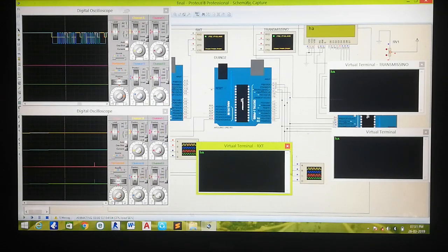Okay, this is the thing, and over here is the display part, so whatever I'm typing here will be displayed over here. By using all this protocol conversion, we converted I2C to SPI. This is a major part of our project actually. These 2 wires are I2C and these 4 wires are SPI, so the data coming in as I2C is converted into SPI and then sent to this Arduino. The last Arduino converts this SPI to LCD screen data, so that the data is printed at this point, okay?